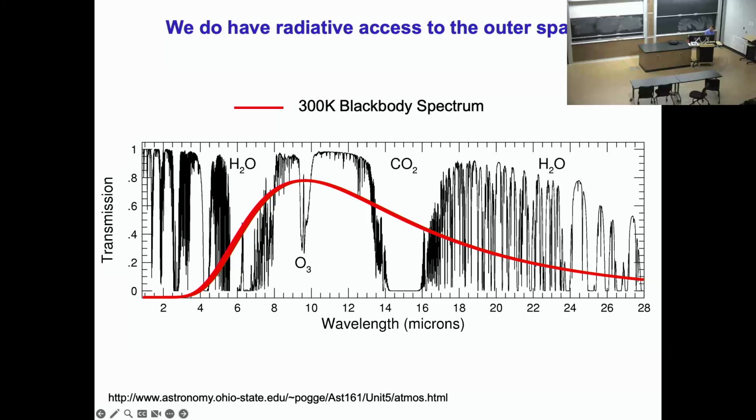Now, the implication of this graph is that if you have sky access, in other words, if right now you go out of this room and go outside, then you would be able to radiate heat out through the atmosphere to outer space. And since the outer space temperature is very low, this represents an intrinsic cooling mechanism. Now, this is, of course, a textbook example of thermal radiation.